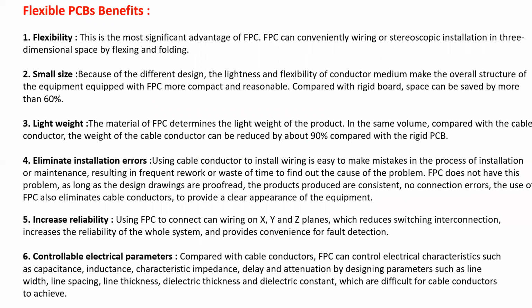We can now look at some advantages of flexible PCBs. The first one is flexibility, which is the most significant advantage of flexible PCB. Second, it is small in size compared to rigid PCB; it occupies only 60% of the space. The next point is lightweight. The material of flexible PCB is light in weight, so the cost of the product is also reduced.